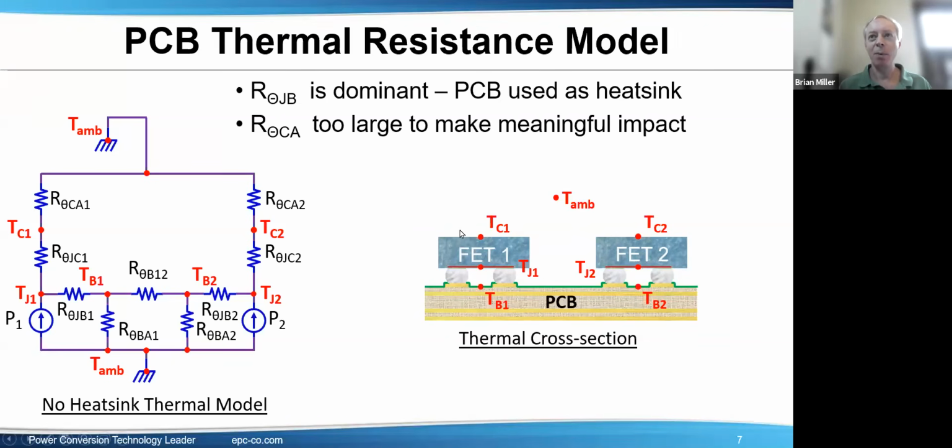Power MOSFETs, of course, are lateral MOSFETs, but the high power MOSFETs are vertical devices where you have current come, say, in or out of the bottom, go through the device, and then come in or out of the top, and you'd have a lead frame or some way of getting the current from the top back down. So that requires some kind of device, typically a package or something over top. Even a metal package has to have insulation layers, and there are other layers inside a package. So it's not simply a metal plate mounted on the top of the MOSFET.